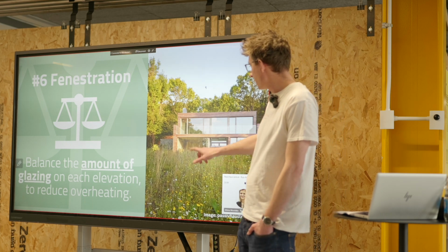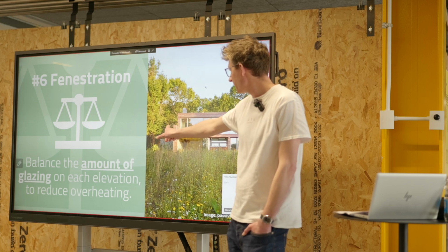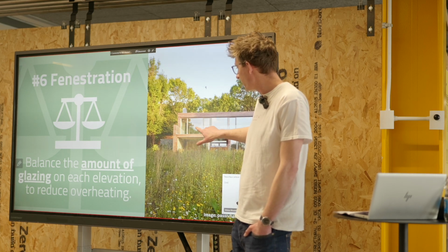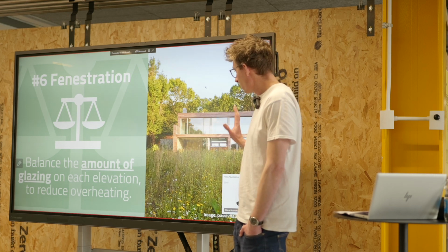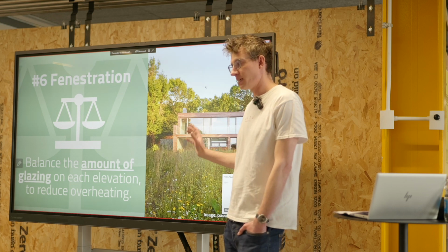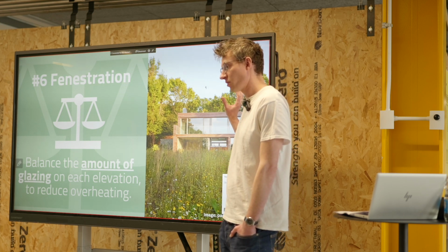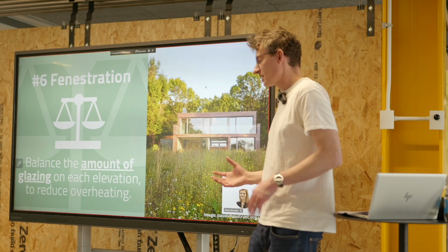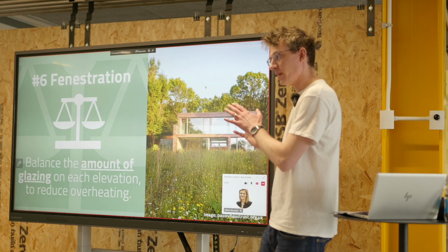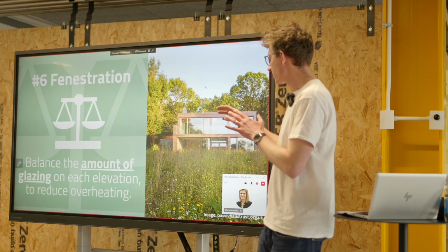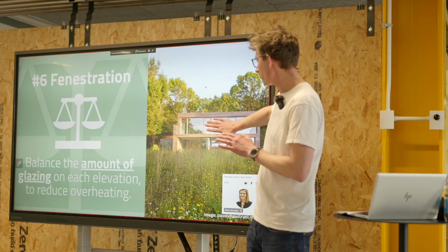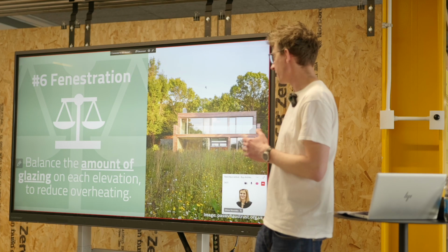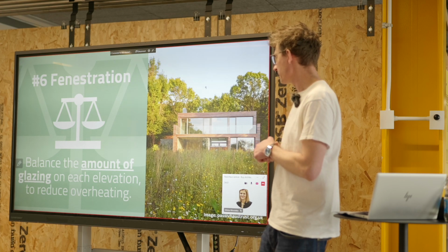If you had a window, for instance, on the side of this building here, and then a door there, and you were to open up the door and the window, all of a sudden you get a much better natural ventilation route through the building because of the differential of air pressure. That's basically due to the natural winds that are surrounding the site. By having two openings on the same facade, you don't achieve anything near the same amount of cross ventilation, basically.